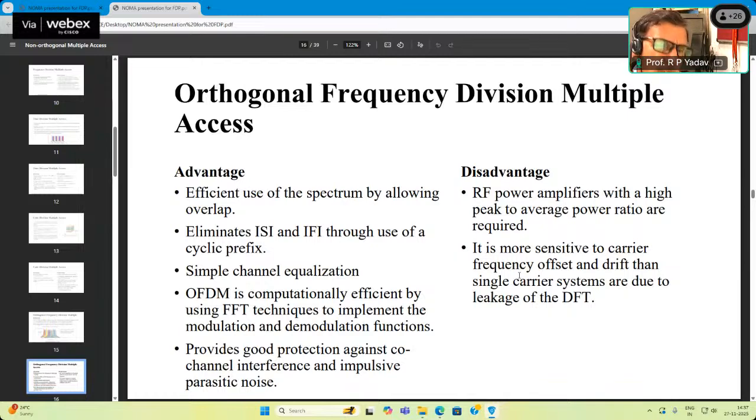Because if you look at transmission, you transmit a binary pulse, 0 1, and if you look at its frequency domain spectrum, then obviously it is almost infinite. So you have to do a little bit of pulse shaping also, choosing a kind of pulse that consumes less bandwidth, and then those pulses can be supported on the channel. But in OFDM also, this channel equalization is necessary, given the channel conditions.